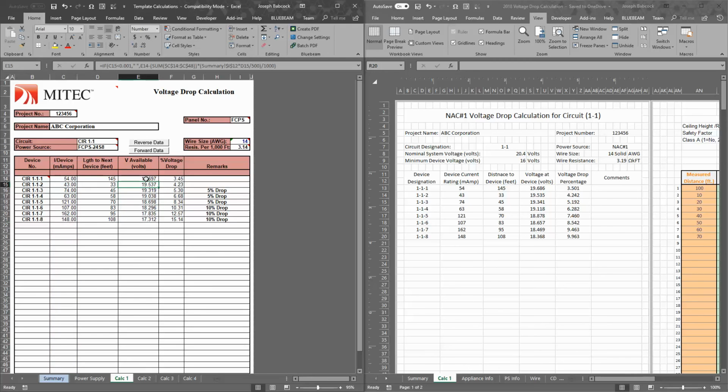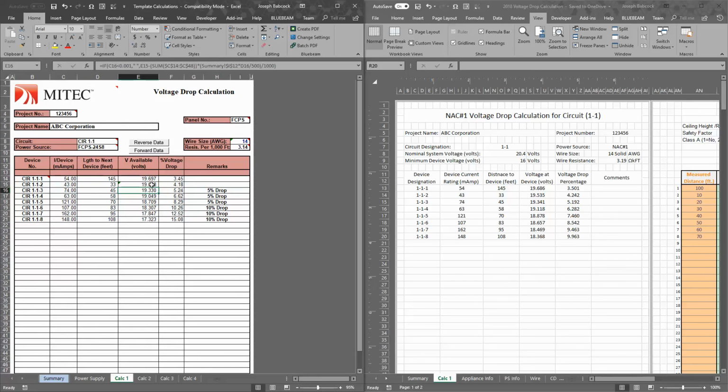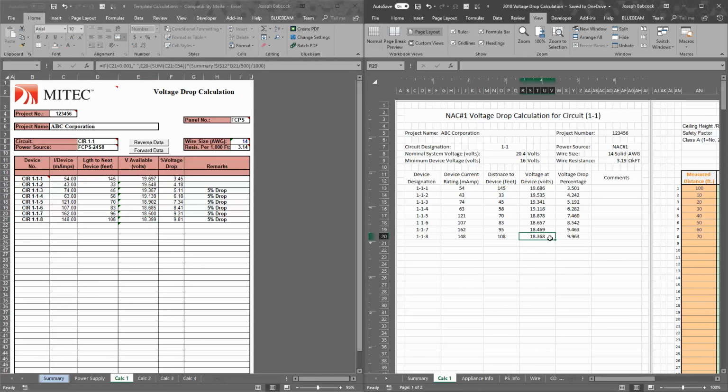So if we were going to correct that, we would correct that from here. So if I remove this formula, just for illustration purposes, and then I show that we calculate everything down. So now we're just doing whatever step we're on, and then we're calculating down. So now we see that that is under our 10% voltage drop, and then we're only at 18.339.